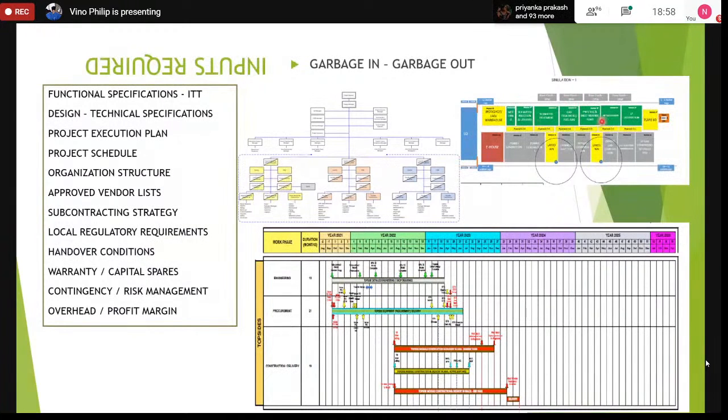And then we can bring the Brazilian modules from Brazil. So the project schedule will have to bring the Brazilian modules over to the shipyard for integration. So we call that the integration process. So we integrate the modules on the deck. And then the Chinese modules are brought from China to the shipyard, which generally is for us in Singapore. And then we integrate it at the shipyard. So that's the whole process of assembling the topsides on a converted vessel.